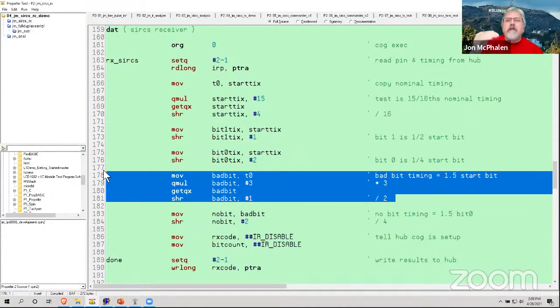When it bypasses it, we allow more current through the LED. So that's our high power mode. So there are actually two outputs in the tagger to do the IR. But again, we're pumping about an amp through the diode when it's on. Now it's on for a very, very short period of time and it can handle it. And remember these pulses, the longest pulse that we're sending is 2.5 milliseconds.